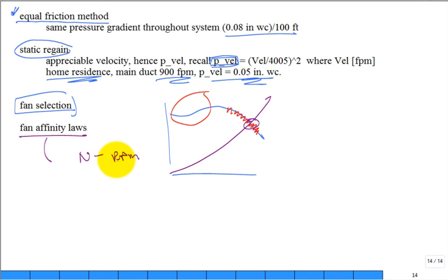What are the key performance metrics or measures for a fan? Three things. The volumetric flow rate, the flow rate. What's the next one? Just like in water systems, it'll be how much energy the fan was successful to push into the fluid stream. That's usually measured in energy per unit volume. That would be maybe pressure gain across the fan.